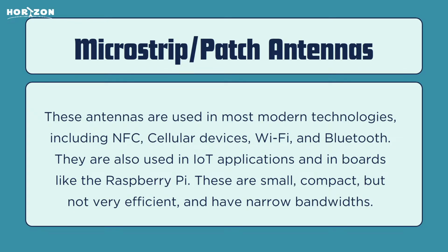In the case of ATM cards or even our own ID card, there is a layer of security after the NFC, so it's more secure that way. And if somebody has used some development boards like Raspberry Pi, you would have seen some metal squiggly lines on a black background. Those are antennas again. Because Raspberry Pis can be connected to the internet, these small, very short antennas can do that work passively. So one disadvantage of these is that they are not very efficient because they're very small and very compact, usually very simple designs, and they have narrow bandwidth, so they can't pick up almost all the radiation that we throw at them.